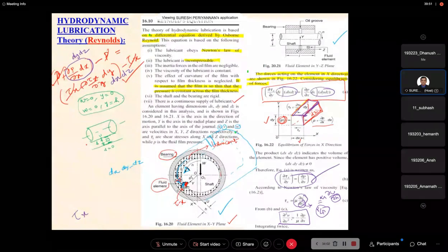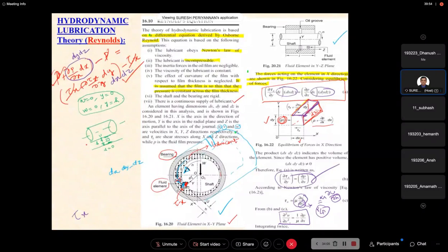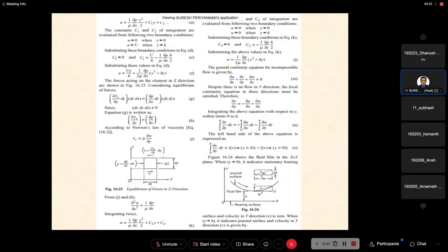From this second order partial differential equation, I am able to find the fluid velocity u in the x direction. This is a standard partial differential equation. Now integrate both sides twice, and we are going to get two unknowns. Then we have to apply the boundary conditions to find our velocity u in the x direction. Finally, after integrating two times, we get u is equal to 1 by mu into dou p by dou x into y squared divided by 2 plus c1 into y plus c2.